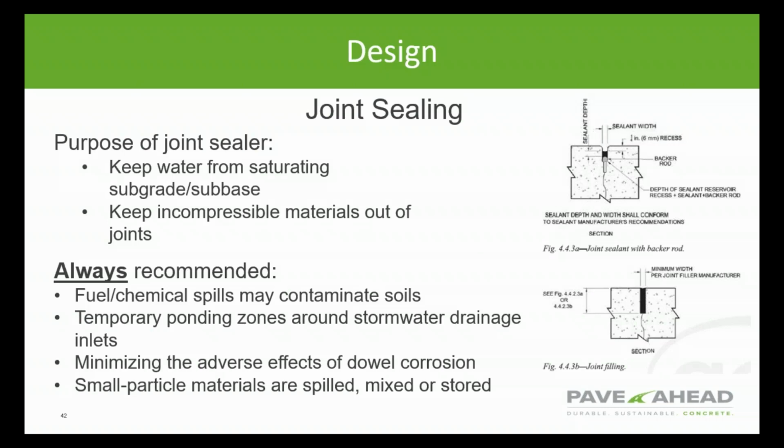So joints are typically sealed for 2 reasons, and that's to keep the water and incompressible material out of the joints.